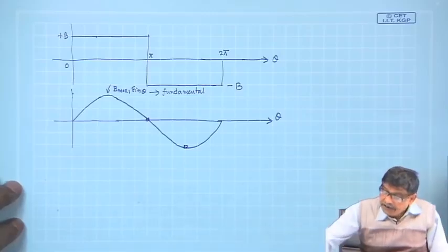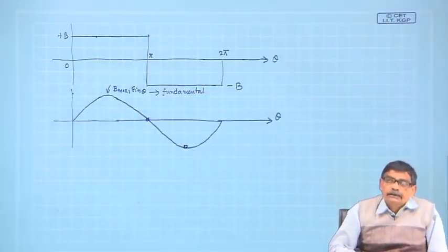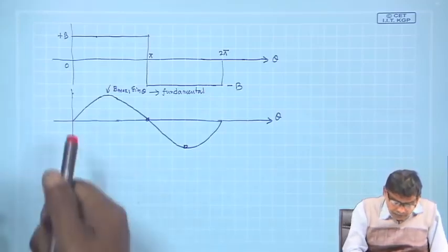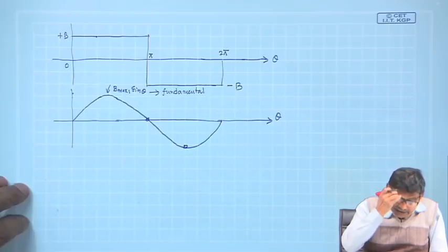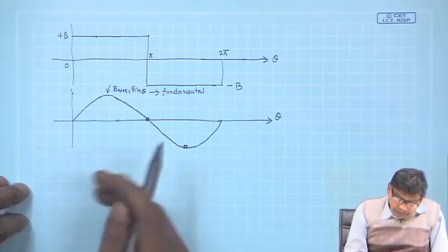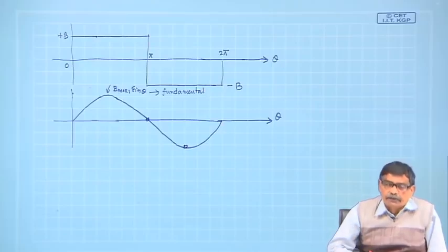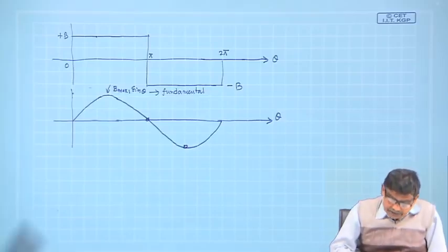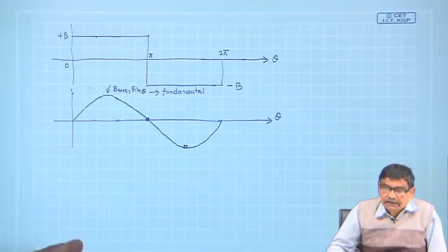Now, the next higher harmonic which will be present will be the third harmonic. Only for that third harmonic I will show you how to calculate the voltage, and then we will be able to do it for other higher order harmonics, for example, fifth, seventh. But I am sure about one thing, that the amplitude of these harmonic components will progressively decrease.